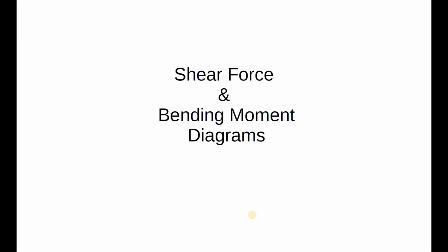Let us now discuss shear force and bending moment diagrams using an example. Before we take an example, let us try to understand what shear force and bending moment diagrams are. Shear force and bending moment diagrams are graphical representations of shear force and bending moment distribution within the structural elements. These diagrams visually represent the flow of external forces within structural elements. They give a clear idea of how external forces get transmitted to the supports through the structure.